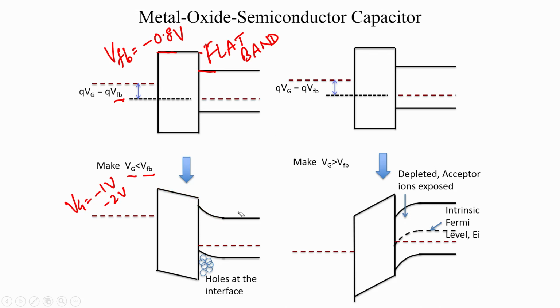And when we start making Vg less than Vfp, this band bending is going to encourage all the majority carriers, since you remember this is a p type semiconductor and it has got a lot of holes. Okay. So, for example, if it is doped with dopant concentration of Na, and if all these dopants are ionized, then the hole concentration is about Na, if Na is much greater than the intrinsic carrier concentration.